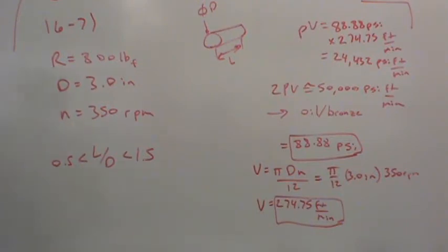I'm trying to remember if these are diametral clearances. It shows at the bottom. You said 4 thousandths? We're saying about 2.5 thousandths. Okay, so you got 3 inch, you come up to a rotational speed, revolutions per minute, RPM, 350. You're about between those two.